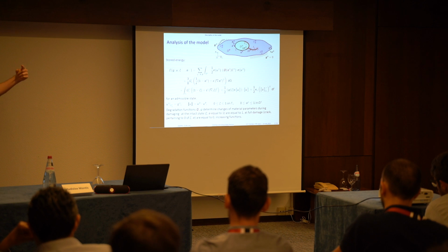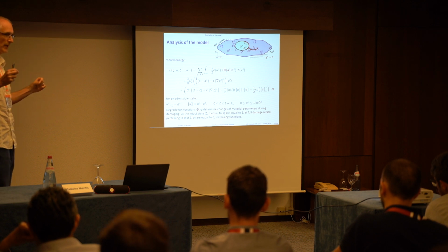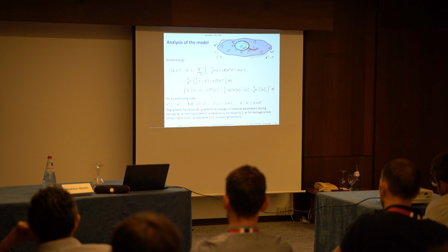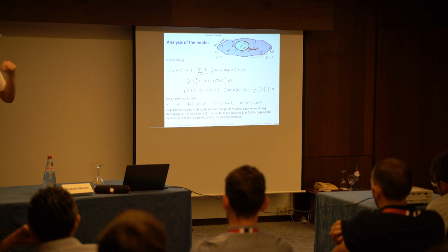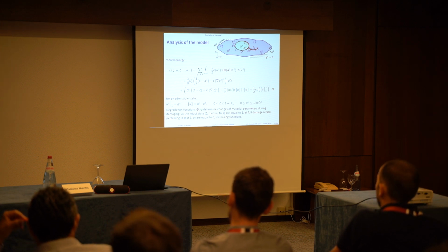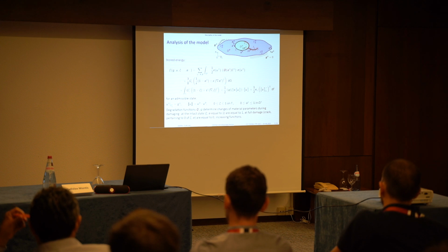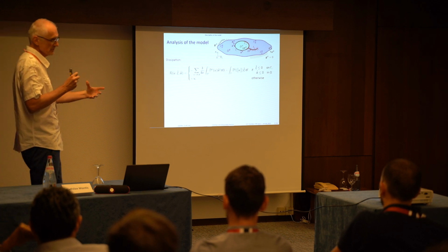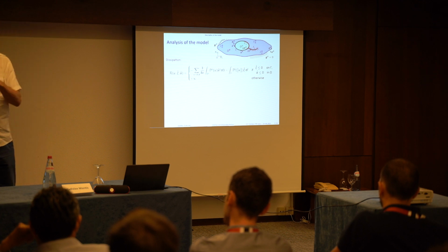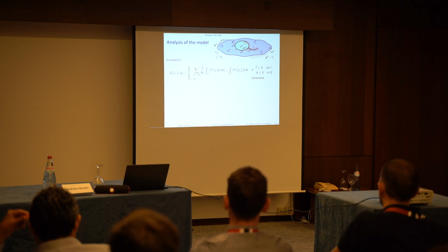Nevertheless, when I'm talking about this description, we need to provide the unidirectional character of the crack, which can be done together with the fact that when I want to simulate multi-axial loading or mixed mode type cracks, which may arise for various loadings. So I need some additional dissipation, which appears when the crack is in a shear mode, which may have various physical context.